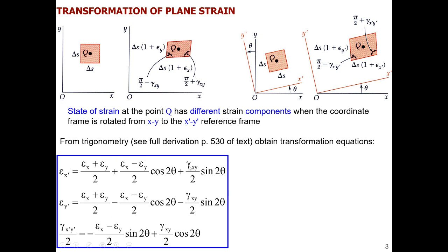If we look now into the structure of this, what we immediately will realize is that the system is very similar to what we already had for stresses. And this makes sense because basically stresses are related to strain by a linear law. So there is a really linear relationship between stress and epsilon, and so that's why these equations are similar. They're similar, but they're not identical. So you can see that there is that factor 2 that appears, for example, with the shearing strain gamma xy, and this is because of how we define this gamma shearing strain through the change in the angle.